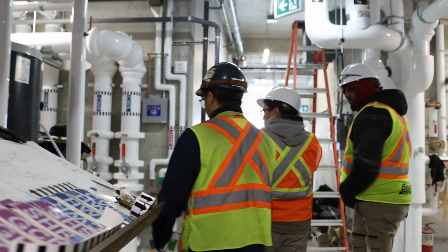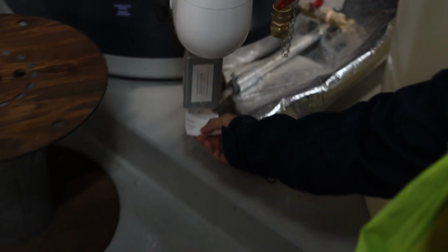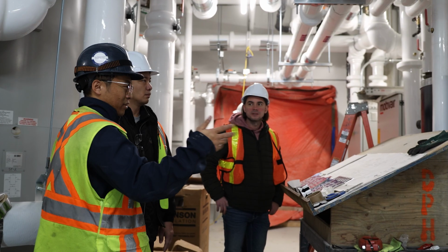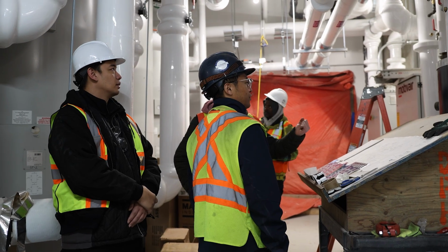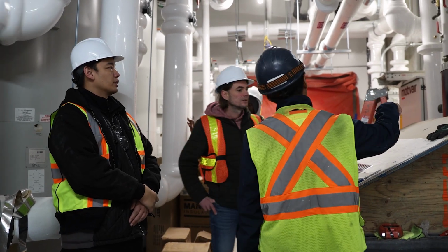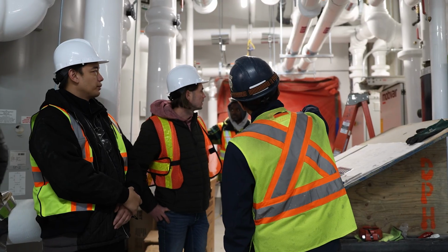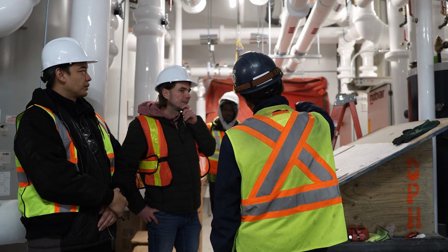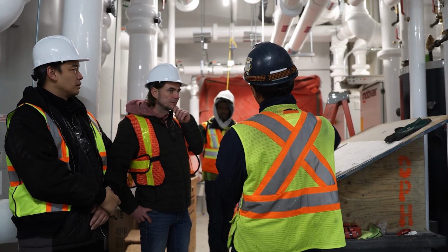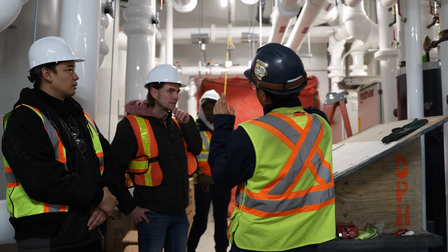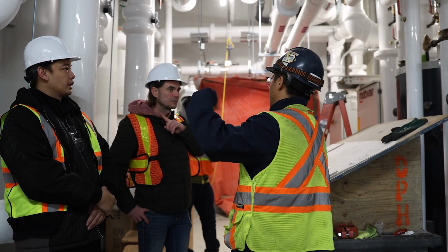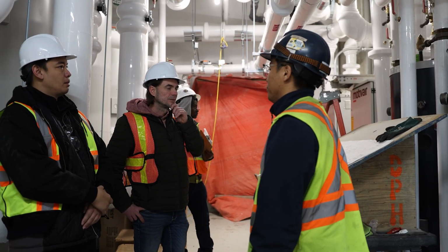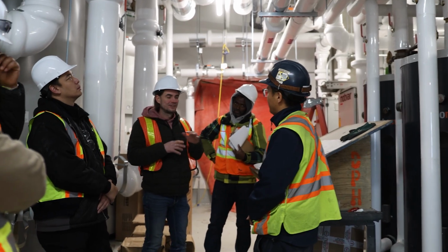Our temperature sensor is right here, a storage tank 5 to 10 temperature. Domestic hot water storage tank. No, this is just for the storage. So the heat is coming off the water-to-water heat pump, or if the water-to-water heat pump fails, the heat will be coming off the boiler, the primary heating loop. It could also be mixed from the solar panel.